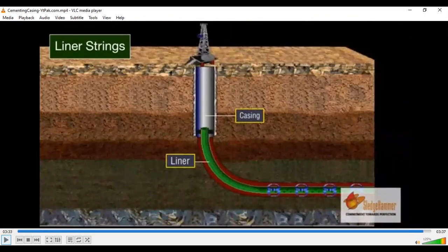Plastic pipeline, we are dealing with the life of the well, let's say 50 years. Can the plastic handle 50 years? Okay, this is one question. Second question, what if there are high pressure zones behind the formation? Can plastic handle that? What if a pressure buildup or blowout happens and these plastic pipes would not work?